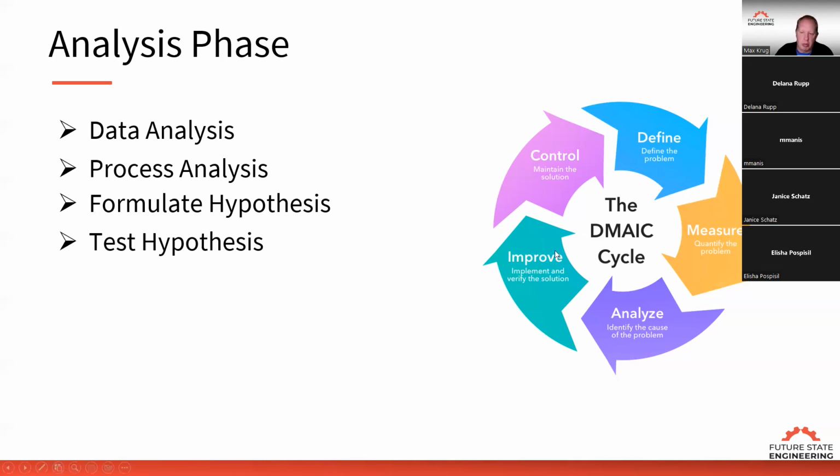And when we're going through the Six Sigma process, just like problem solving, we're going to spend the majority of our time in this define, measure, analyze stage, right? In that process characterization we talked about, I spend probably 80% of my time in that stage and 20% in the improve and control. Because if we really understand the process and where the variation is coming from, and we do our homework and formulate our hypothesis and test it, then we're guaranteed that when we make the improvement, the variation is going to reduce. So we want to spend most of our time in these first 3 steps.